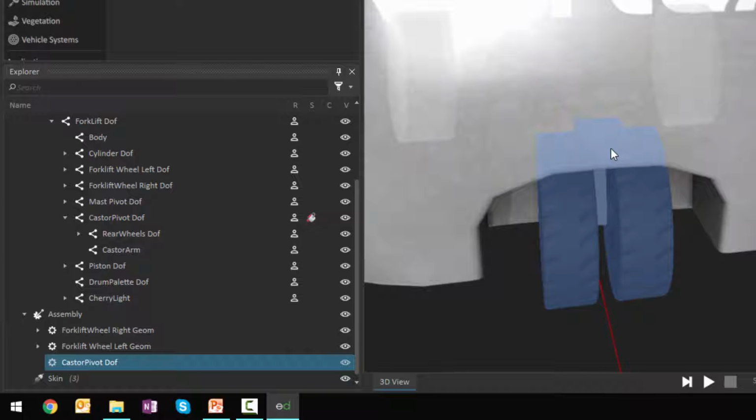Sure, I could go in and want to create a small collision geometry around this arm that we have here for the pivot. Now, that being said, that arm is never going to be colliding with anything else within the environment. So there's no sense in actually going in and defining something like what is the collision geometry for that part, since it would just add extra computations that are not really required.